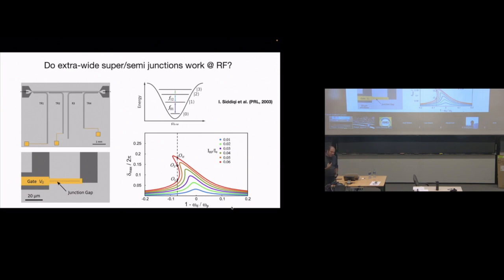it turns out if you have an oscillator, which is a harmonic oscillator, a resonator, right? If you drive it with high power, it becomes a very specific object. It becomes a very nonlinear object. And this nonlinear object has a universal, basically, relationship between the power that you put in and the frequency that you measure. And if it is following that rule, it basically means that there is no other funny business going on with the dissipation of that junction.